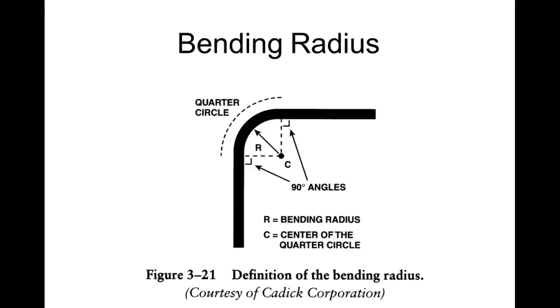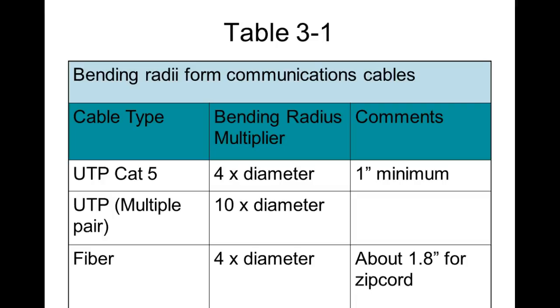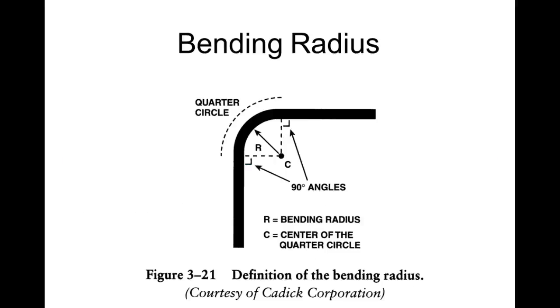or something that's going to move around a lot. A lot of times we use flex conduit. And then I don't know if we got any raceway over there. This is actually the end of the conduit. And what we'll do here is we'll start talking about some of our communication cables. So what we'll have to do next class is talk a little bit about impedance and characteristic impedance of communication cables and stuff like that we have to make sure that we maintain.